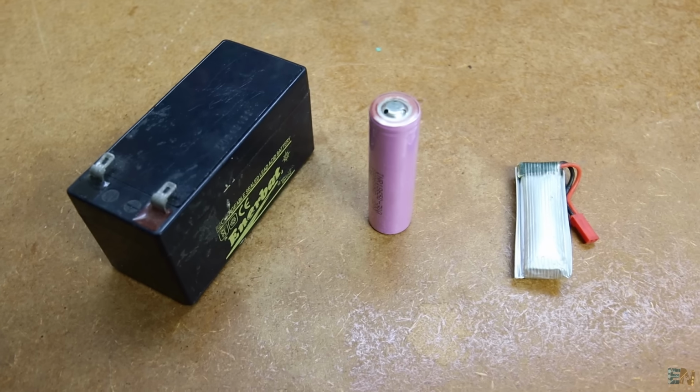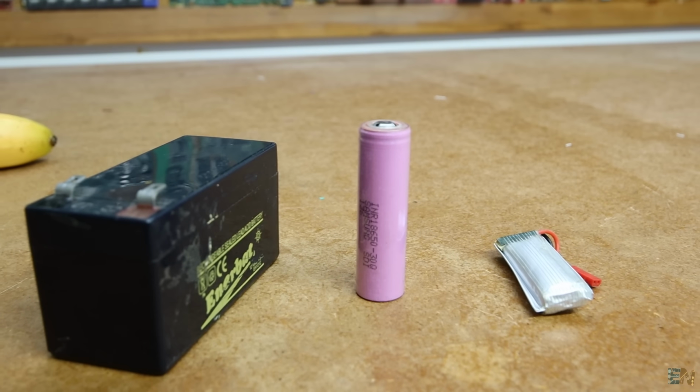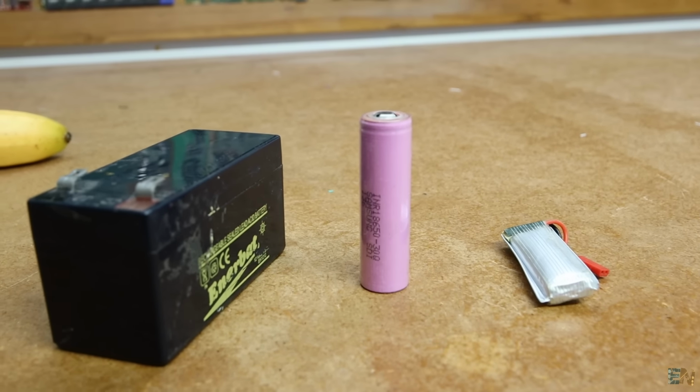So that's why I told you that the difference between the voltage of the battery and the input is very important. Because it's very interesting: if you have a battery that is 80% discharged, so it's almost empty, it will charge a lot faster than a battery that is only 50% discharged, so it still has half of the charge. That's because of the voltage difference between the input, which is 25 volts, and the output, which in this case, let's say 50% is 7 volts and 80% is only, I don't know, 5 volts. These are just imaginary values.